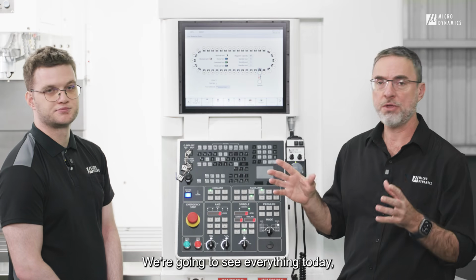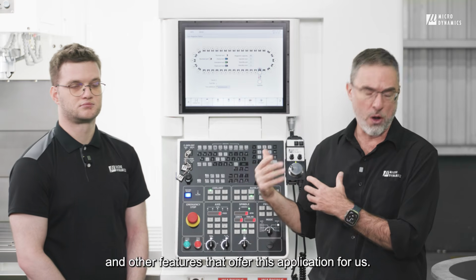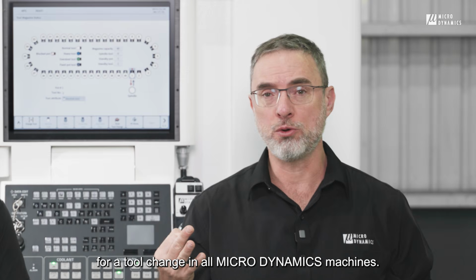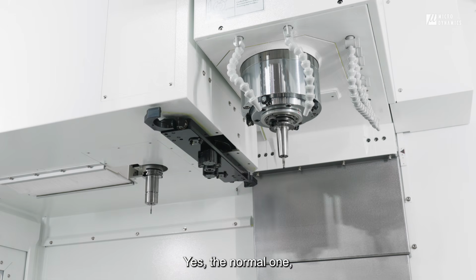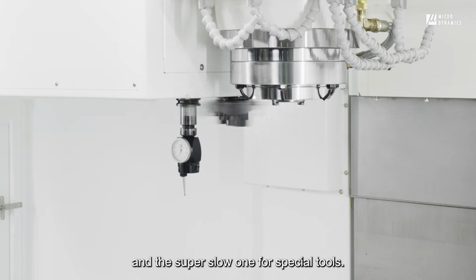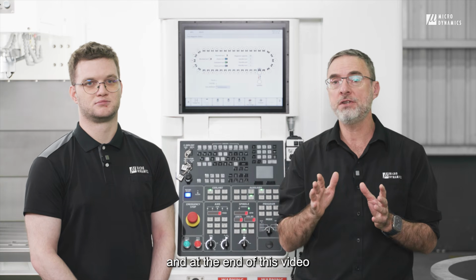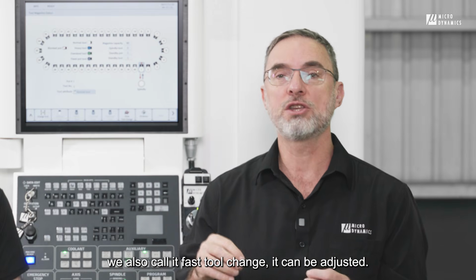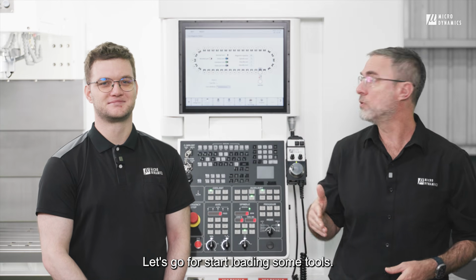We're going to see everything today, like the different speeds for the tool changer and other features that this application offers us. There are 3 different speeds for a tool change in all Microdynamics machines: the normal one, the heavy tool one, and the super slow one for special tools. Now we are going to see how to use the 3 of them, and at the end of this video we are going to talk about the normal speed, because the normal speed, which we also call fast tool change, can be adjusted.